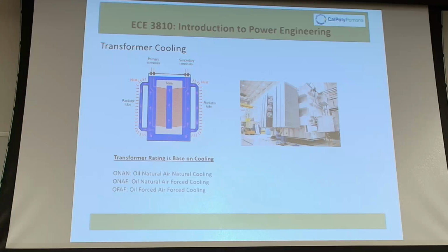Basically, they bring the truck, hook it up, and drain the oil if it is damaged. On very large transformers, especially now, they use what they call DGA, dissolved gas analysis, where they're constantly analyzing the oil and its quality. The problem is that if you get moisture in the oil, or if the oil starts breaking down, you can have a flashover internally and the transformer is done.